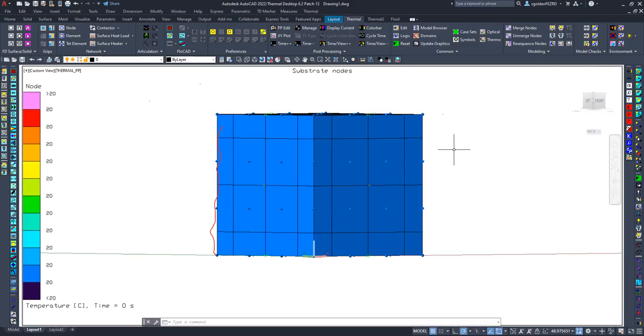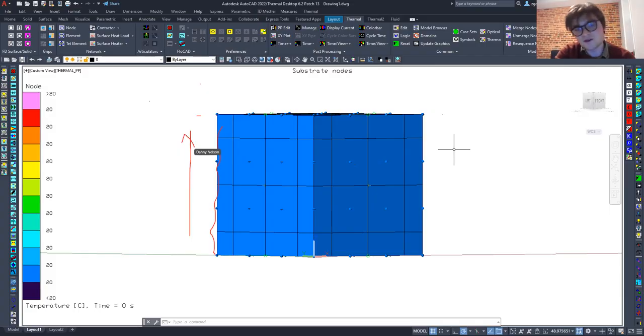There we go. 1, 2, 3, 4, 5, 6, 7. Okay. And then the end caps. So you have like 9 in total, basically. So what you want to do, way back when we first defined these faces, we gave it 4 nodes in this direction. But in reality, you're probably going to want about 9 nodes in this direction, because when you add those thermal contacts between a card that's sitting right here and all these edges, you want the nodes here to be pretty close to the nodes here for the most accurate model.